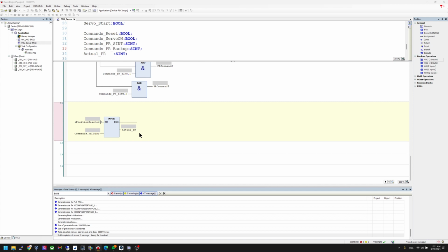I would like to move to station 1, and when the servo drive detects it, I send back a finished signal to you, then you can know now your servo drive has finished its task, and it should be station 1. And so if you would like your drive to go to station 10, you send the station 10 command to your drive, and the drive sends back a signal called motion task finish. Then you know now you're in station 10. So it's a very simple logic, but very common when you control a servo drive.